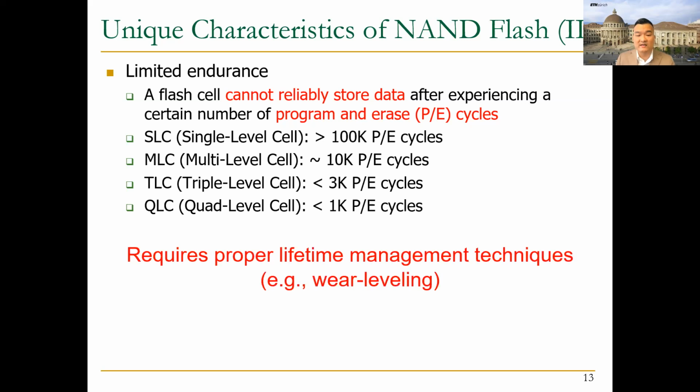So a modern SSD requires proper lifetime management, such as wear leveling, that aims to evenly distribute the P/E cycles across all blocks in the SSD. And this is necessary because if only a small portion of blocks, let's say 10% of the total blocks in the SSD, becomes unable to use due to high P/E cycles, it may also make the SSD unusable, since the SSD cannot provide the specified capacity any longer.